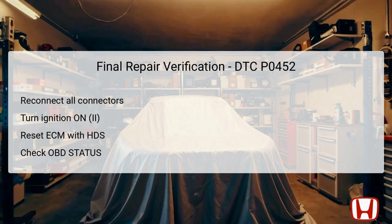After completing all necessary repairs, verification steps are essential to ensure the issue has been resolved. Begin by turning the ignition switch to the lock 0 position and carefully reconnect all previously disconnected connectors to their respective positions. Then, turn the ignition to the on IT position to apply power to the system and prepare for diagnostic tests. Use the HDS to reset the ECM, which allows it to re-establish communication with all connected sensors and systems.